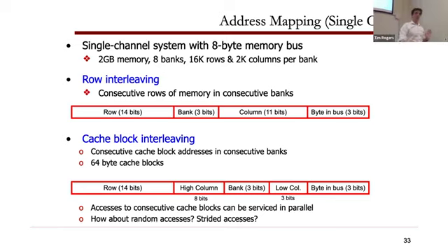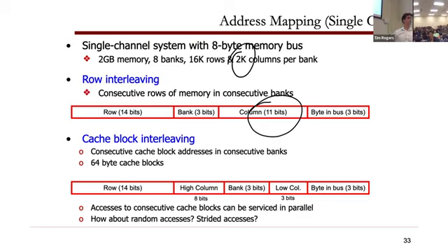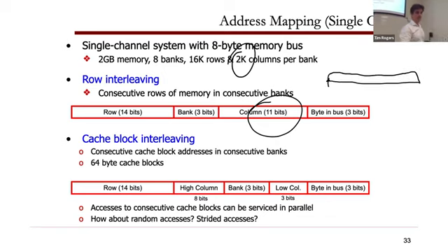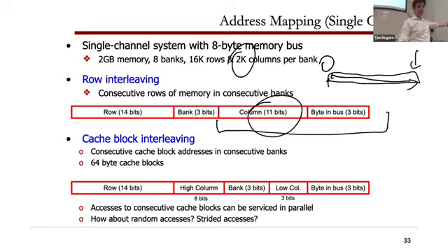Okay. So now I put 11 bits here. Why did I pull this out of thin air? Where did 11 come from? Yeah, 2000. Because I know there's 2000 columns. So that means I'm going to have 2000 chunks of 8 bytes at a time. That's 11 bits of the address space. So this will take me across an entire row. My address space 0 through the end of the row is all going to be contiguous across one row with this particular mapping.